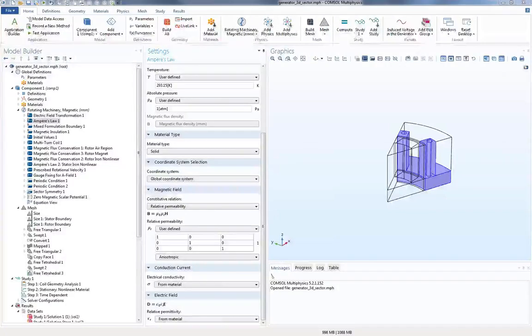Let's take a look at some of the questions here. There is a question from Antonio. Can we model a vibration of the motor? Yes. If you want to do a vibration study on the motor, there are a couple of things you have to do. COMSOL has the Acoustics and Structural Mechanics modules. These are the 2 modules that you would need. First of all, there is electromagnetic force that induces structural stress, and you can use that information to feed into the acoustics to simulate the vibration.